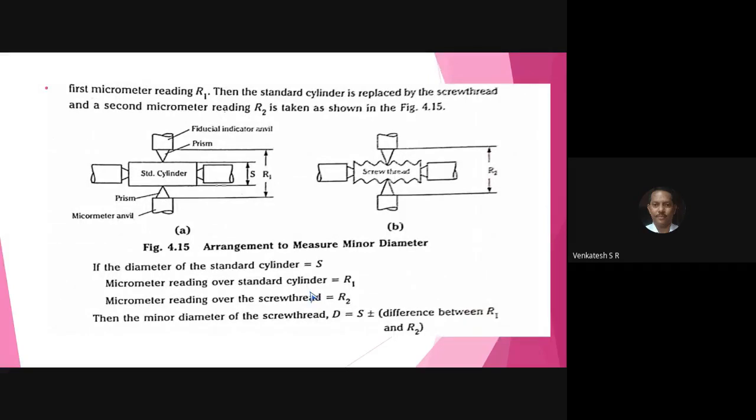Say, in the metrology lab, how do you measure the major diameter, minor diameter, addendum, pitch of the thread? For that, we have the screw thread measuring caliper, or you can fix the thread of the component in the two anvils of the screw measuring instrument, where this is the cylinder and this is the anvil. You can fix it in between the two centers.